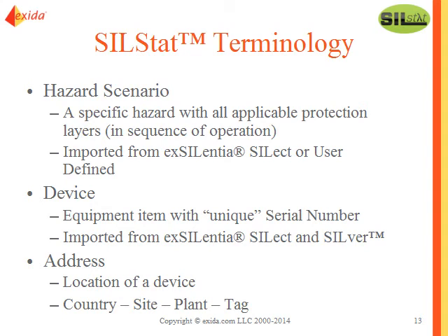There's a couple of different terms that we use in SILStat, and I just figured it's useful to express them here so that we're all on the same page in case I refer to one of them later. So we have a hazard scenario. A hazard scenario refers to a specific hazard with all applicable protection layers in sequence of operation. So a hazard scenario could be overpressure in a vessel, where a control function interlock is the first layer of protection, followed by an operator, followed by a safety instrument function, followed by a relief valve.